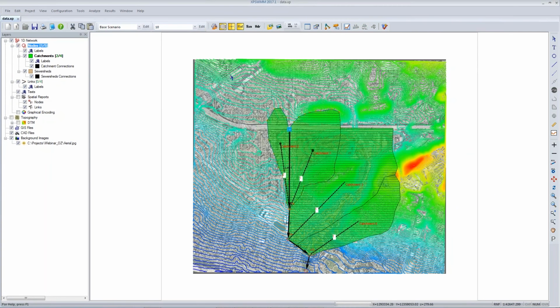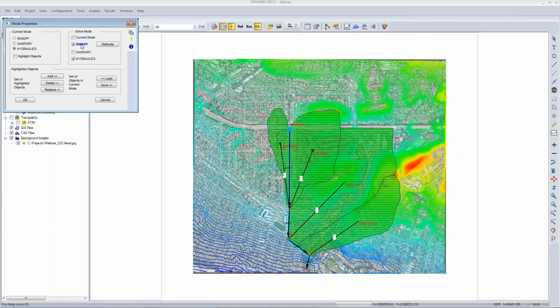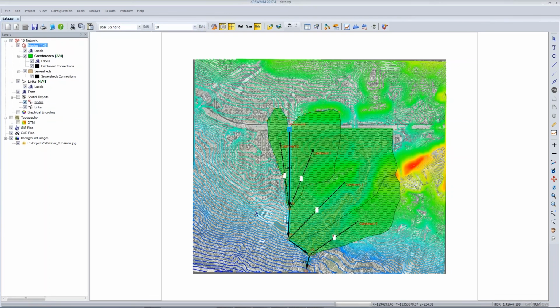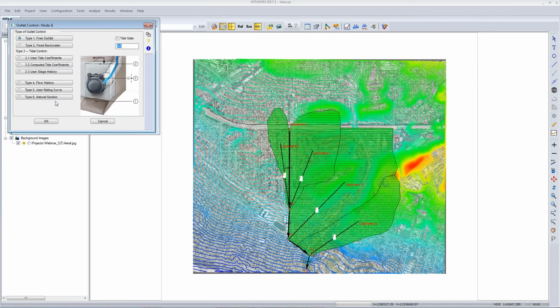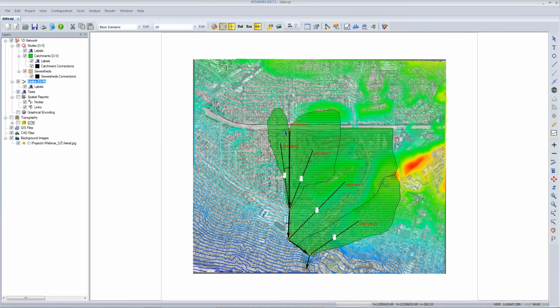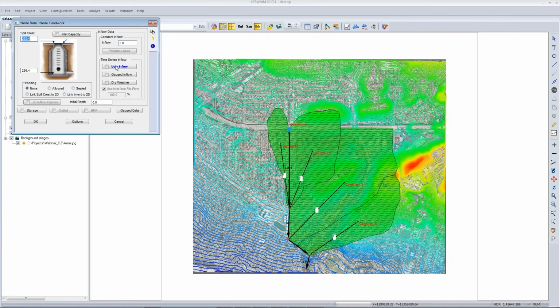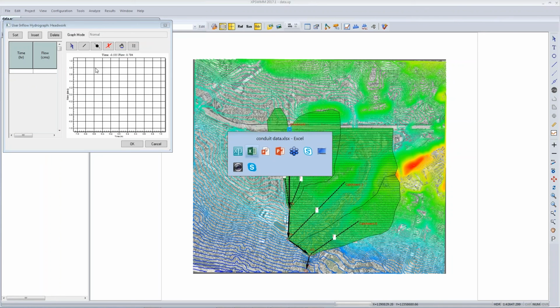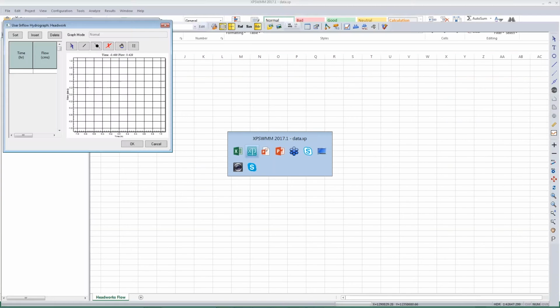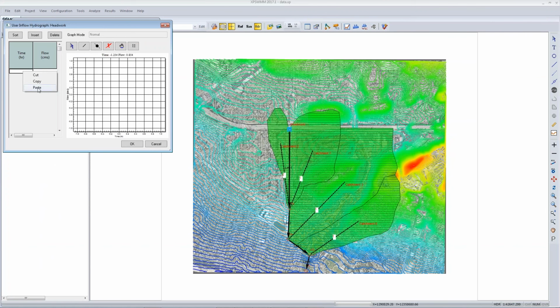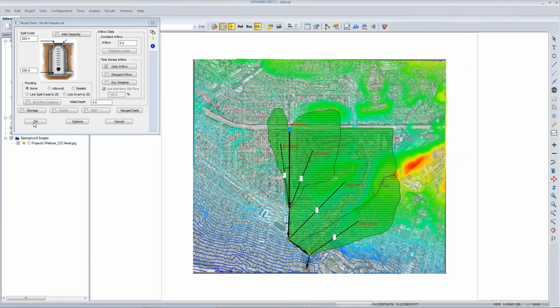So in the runoff mode, you won't want to have any of these links active, but you would want to have all of your network active in the hydraulics mode. Let's switch it to solving both the runoff and the hydraulics simultaneously. Excuse me, we're going to need an outfall. Clicking here, a free outfall, and let's copy and paste to the user inflow my offsite hydrograph that passes through. It's here, I can copy, and I'll paste it here and click the OK button.